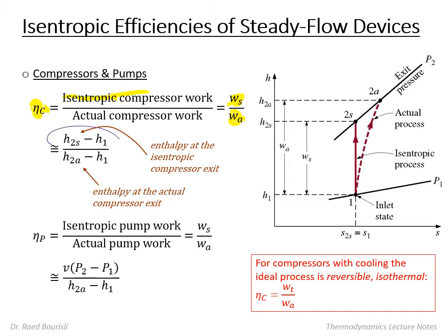So this is the opposite of the turbine. So this is the isentropic on top and the actual at the bottom. You see the HS diagram here, that from going from pressure 1 to pressure 2, from this isobar to this isobar, instead of the thing being isentropic, the entropy increases actually for the actual case, and the actual enthalpy, or basically the temperature of the fluid at the exit of an actual compressor is greater. Okay, and the work required is greater.